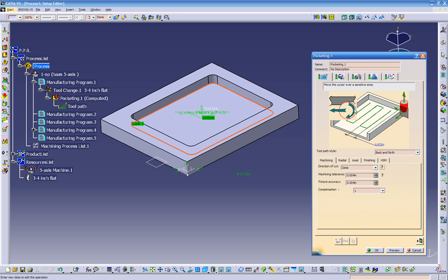So the end mill rotates clockwise, and it's moving forward this way. See the arrow going this way, and the tool rotates this way. So everything is climbing. I'm pretty sure that all the programmers out there know that most of the programs need to be climbing. Rare we find programs where we get a nice finish using conventional. So I very rarely use conventional. I always leave this on climb all the time. I never change it. Over here is the tolerance. You can see over there.